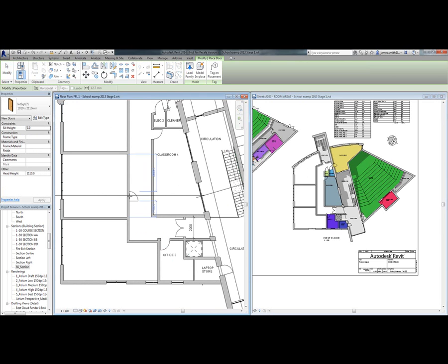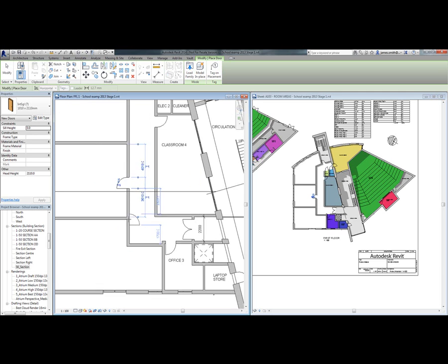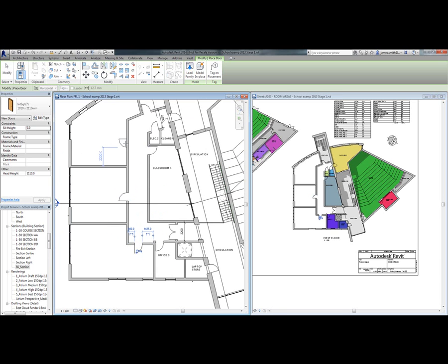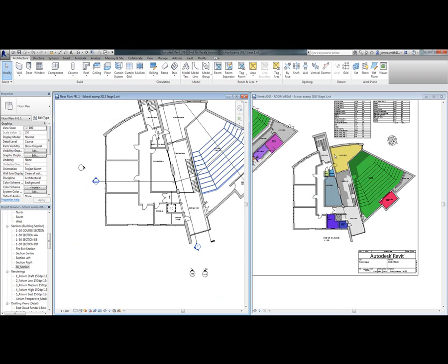So if I put a door on here, again, I'm just going to put it in position. You can see here it's snapping, so I can have whichever side I want. I can change this, so you can see I can just select the little functions there. And I can also change the way in which the door opens. So again, I'm just going to pop a few of these in here. So I'm now building it up, and all the time everything within the project's relating. So even if I've done any studies on the area, such as analysis or airflow or heat loss, this is all going to be updated and be kept relevant.